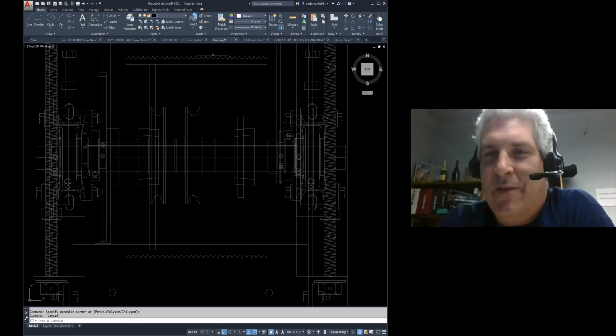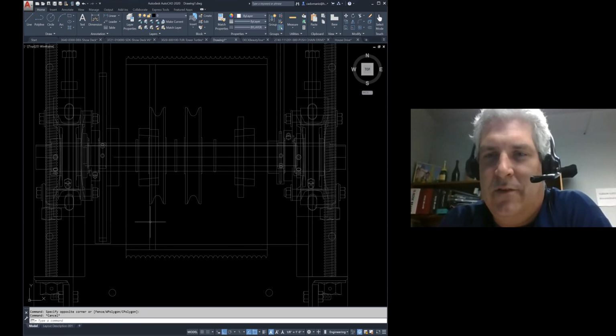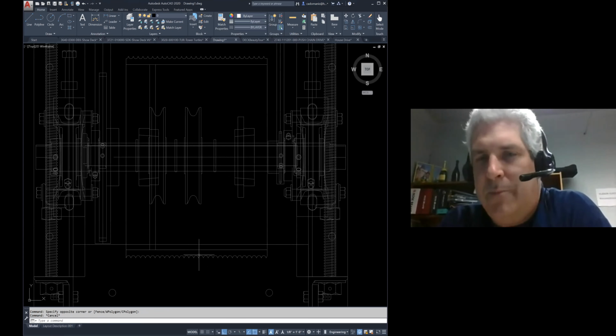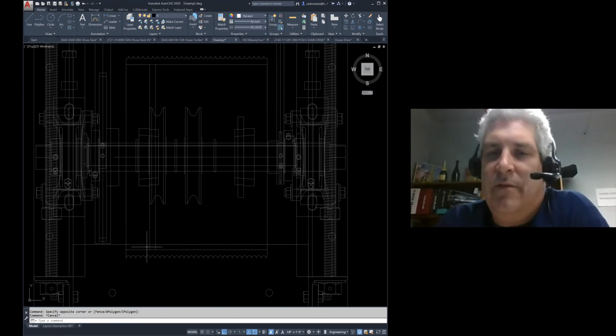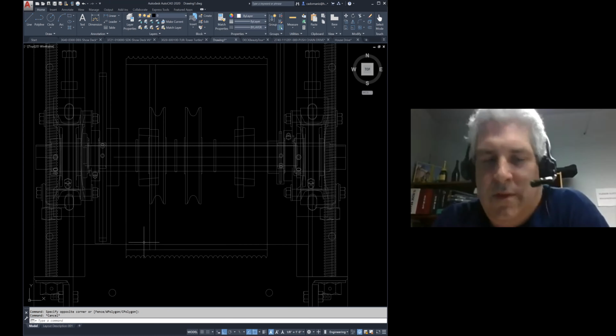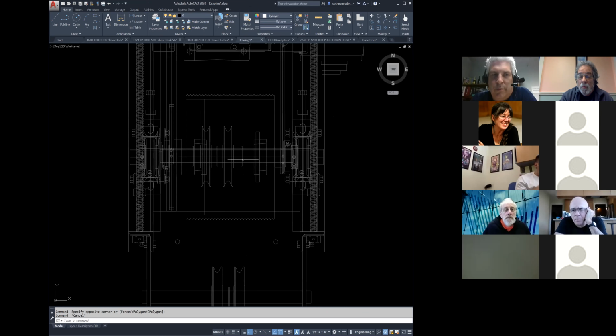Sorry about that. But yeah, just a quick recap, right? We could come in through a groove and anchor into these plates inside the drum to clamp that cable off, or we could simply put a few wraps around on that drum. As I was saying, our preference is definitely they anchor the ends at the machine. That way we know nothing can slip at the machine end of it. And that's how we get our loop and our motion through there.